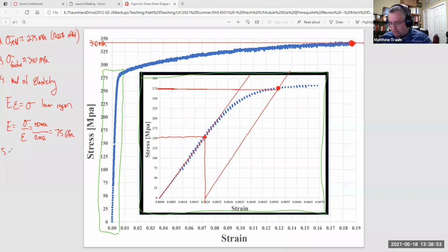And I had to look this one up because modulus of resilience is not something that I would normally use. But interestingly, it's an energy. So all of a sudden I'm like, oh, it's energy. Okay, awesome. I love energy. So the equation for modulus of resilience is 1/2 sigma squared over E. And what exactly is this sigma?